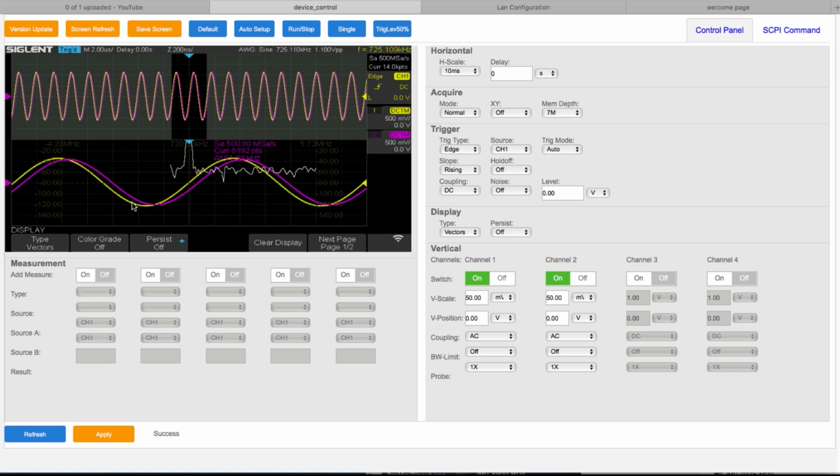as you can see, I've got one waveform coming in. Actually, what I've done, I've got two probes clipped together using the AWG option, the waveform generator, which is an option for the unit, and I've got a capacitor between two probes going from the output of the wave generator to input 2, and input 1 is going straight to the output of the generator, so I've teed off, and so you can see the phase difference there from the capacitor. That's what the capacitor is doing to the waveforms, just in case you're interested. That's why I've got those two waveforms which basically match but are out of phase.